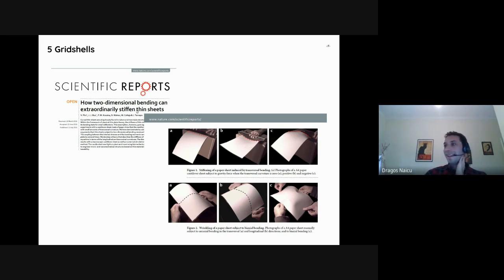If you take a piece of paper and you just cantilever it out, it will just flop downwards. It will not be stable at all. However, if you impart a little bit of curvature in one direction as you hold it with your hand, you will see that it's able to carry its own weight and cantilever out, and it could even carry a small object like a little pin or a light pen or something. So this is a very good example of the power of curvature and how it helps shells carry their loads.